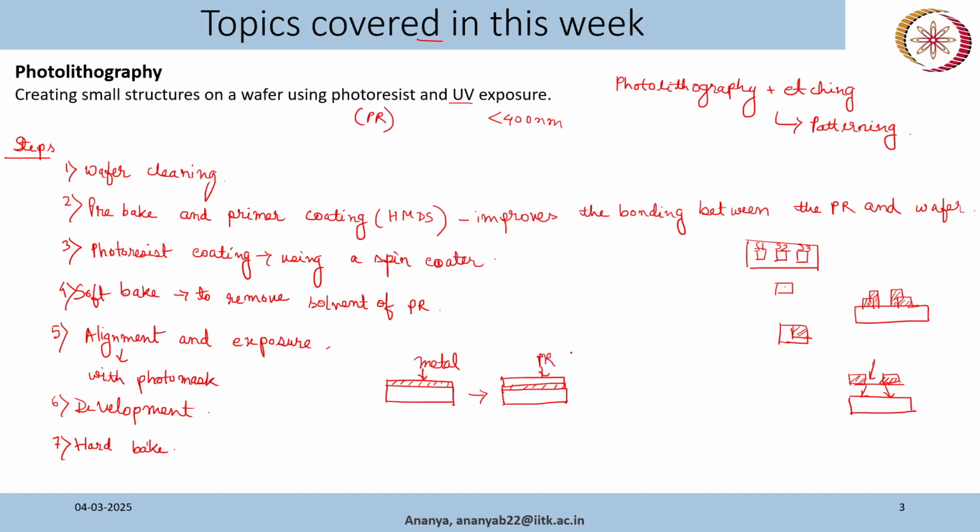The spin coater will rotate at a certain speed, and because of that speed and the viscosity of the photoresist, you will get a certain thickness of photoresist on top of your substrate. Okay. Then you will use a mask that has the interdigitated electrode pattern. Now let's say you are using a positive photoresist. Ultimately you want to pattern this metal layer as an interdigitated electrode. So what should be the mask for your photoresist for this purpose?